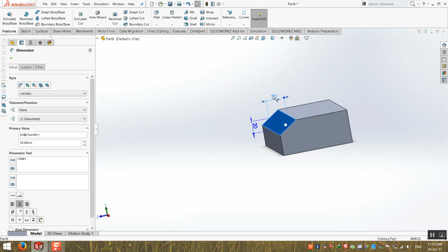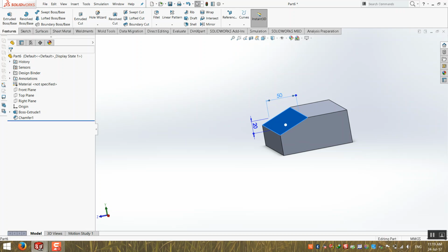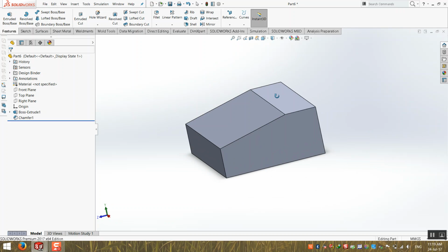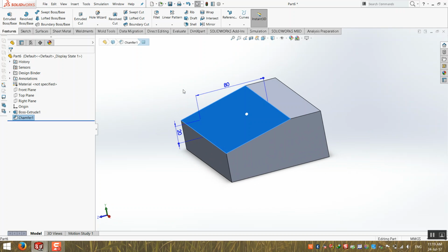Just click on the feature. This is easier. Because mostly, using the angle is difficult to define when you chamfer. You will measure on the top and the bottom. It's difficult to understand the concept of the angle, and from where, based on what the angle is working. It's working on the bottom, on the top, on the side, because sometimes you have no 90 degrees corner, and you cannot determine exactly which flat surface you are working on because you have curvatures. But here you have like 100 options to do things. Okay.